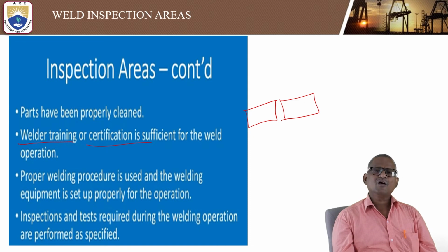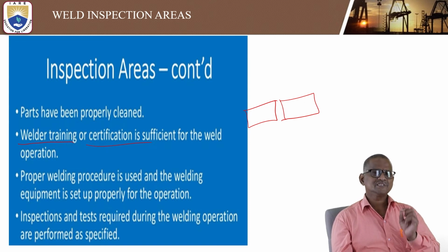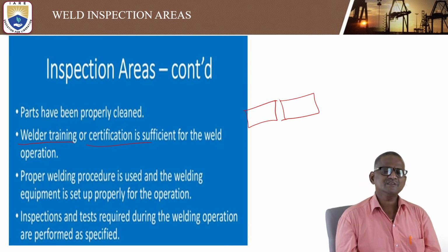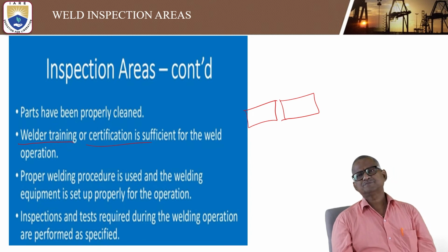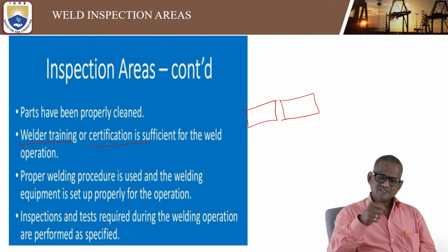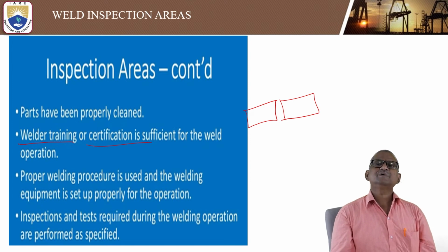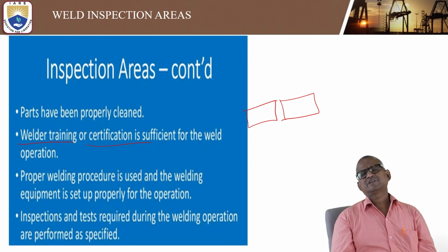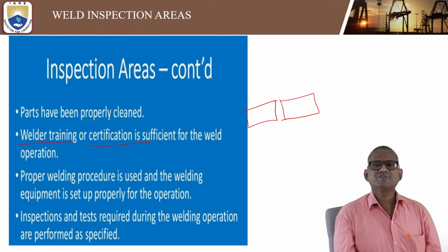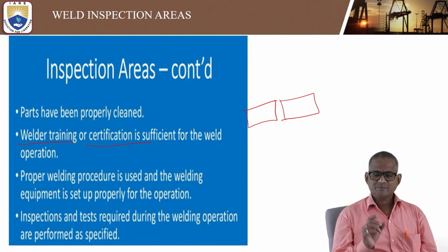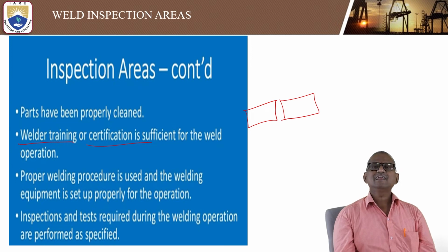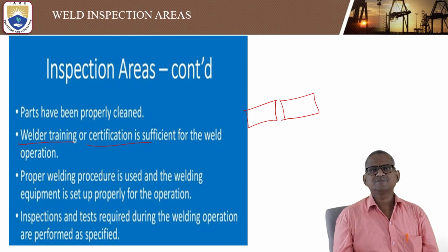So in any component some basic inspection and test should be conducted after completion of the welding operation or during the operation, to be specified, so that after that the chip can be removed with the chipping hammer also. Then after cleaning also with the smooth files will be performed so that good quality can be obtained in the welding process also. So these are the basic areas which is really needed for destructive testing of machines.